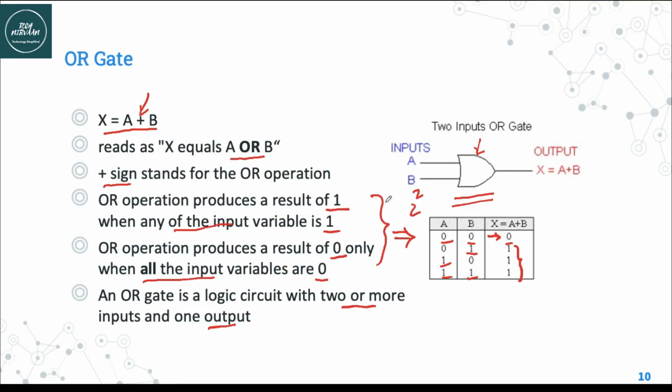So this is OR gate. For OR gate, we will take positive logic system and negative logic system. So in case of positive logic system, we have input A, B, output X. Negative logic system, input A, B, output X. And we have two voltage levels, 0 volt and plus 5 volt.